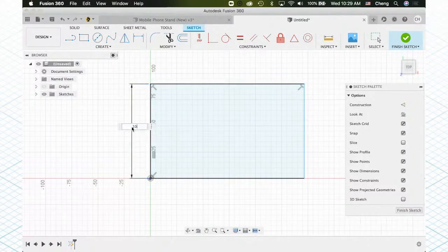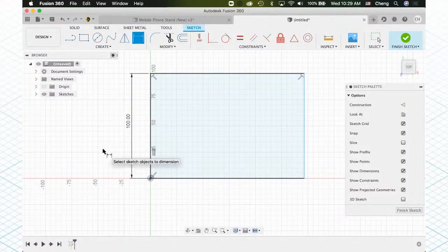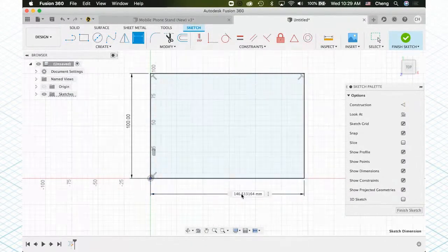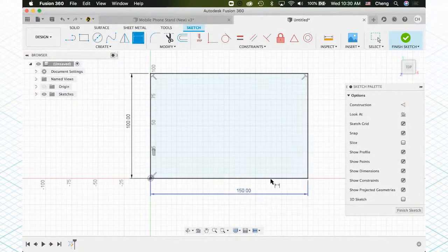to do the locking of the distance. For example, this is to be 100. Once I input 100, do you see the top horizontal geometry? This will become a black line. Same thing when I click the second geometry, and right now both lines are fixed and I have the 4 sides of black lines. So I can't move, I couldn't stretch it anymore. It is being grounded as well.